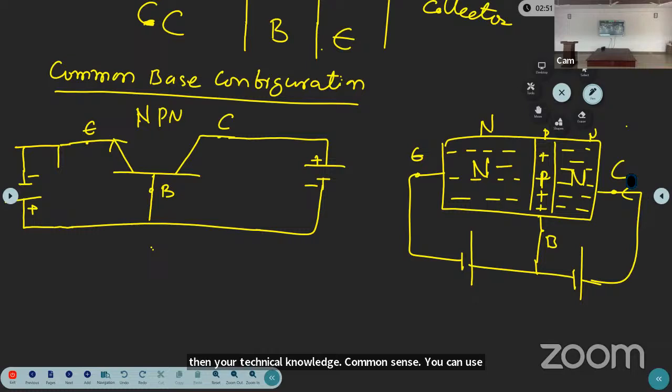By applying the reverse bias, the junction width increases, that is, the junction between the collector and base will increase. Is that increased junction width spreading into the collector and base equally or unequally? Unequal. So what is the unequal ratio? Into which region will the depletion region spread maximum, and into which region will it spread less? Maximum into the base. Why?